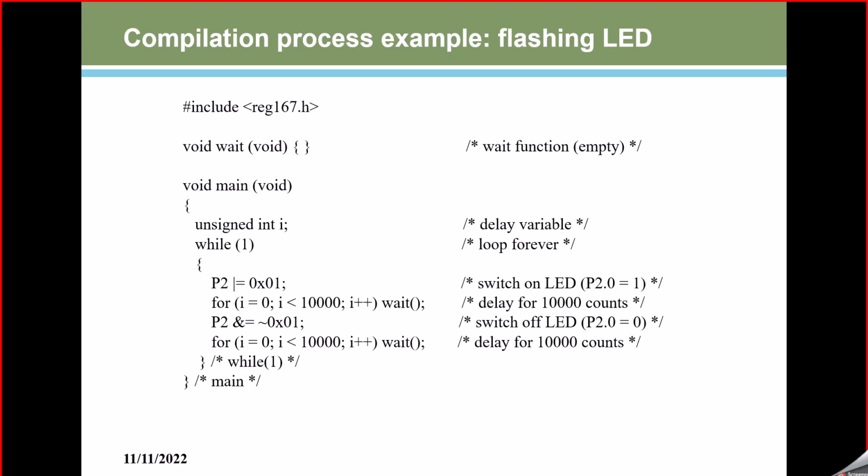If you see this 8-bit data 0x01, if you convert it to its negation, the 1 byte of data 0x00 will be FF. If you convert 0 to 1, you get FF, and 01 if you convert, you will get FE. If you want to check, you can convert this into binary from your side, and you can convert the high to low. This is the output of FE, meaning the last bit they are going to make 0. If I make it 0, then it will become an off state. That will be an on-off, on-off pattern.